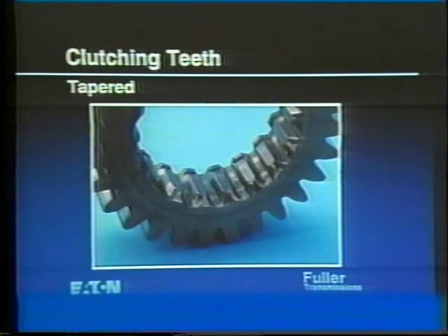The clutch tooth faces can also wear from use until they are tapered rather than straight. Tapering contributes to slip-out, so replace such gears and clutches. Excessive vibration from the engine or driveline will speed up this tapering process. Check for causes of vibration if excessive tapering is found.